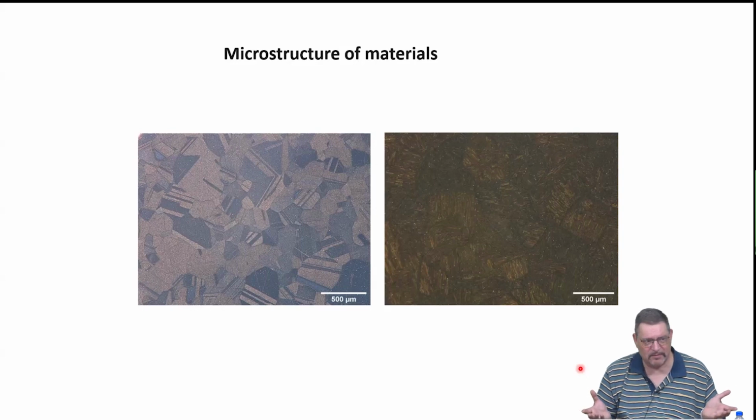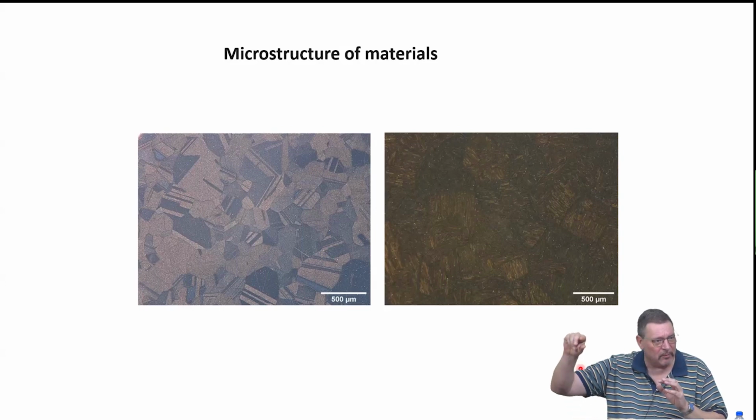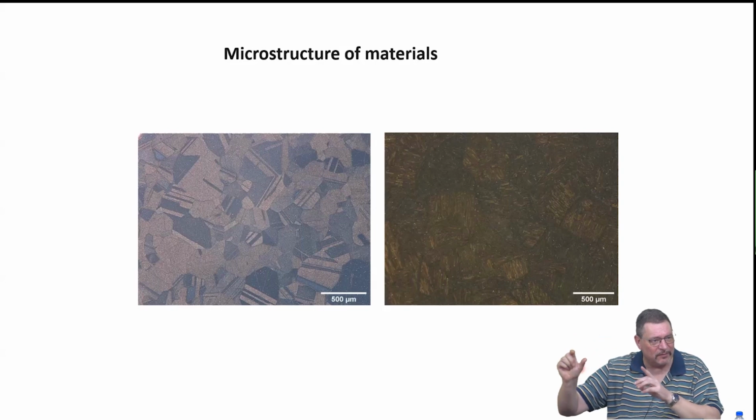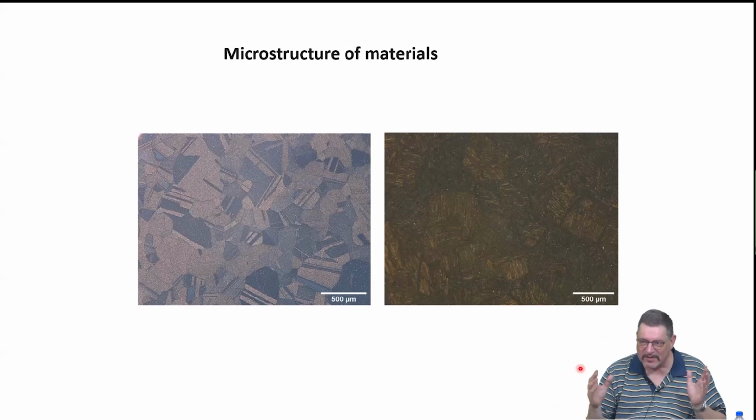Why is this? Well, we can only guess. I would guess it's because of these local distortions. So dislocations cannot easily move through the lattice because it has kind of a different Burgers vector everywhere, right? Because the spring constants are different at each position. And this makes storage of them easier than in a perfect lattice of pure nickel.